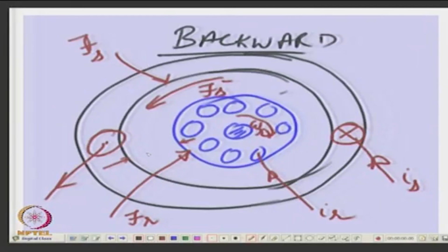If rotor current is 0, rotor iron is dead, it is not magnetized. Now, at each position it has an assumed MMF. Therefore, you have an air gap MMF here, which is Fg. What is Fg?